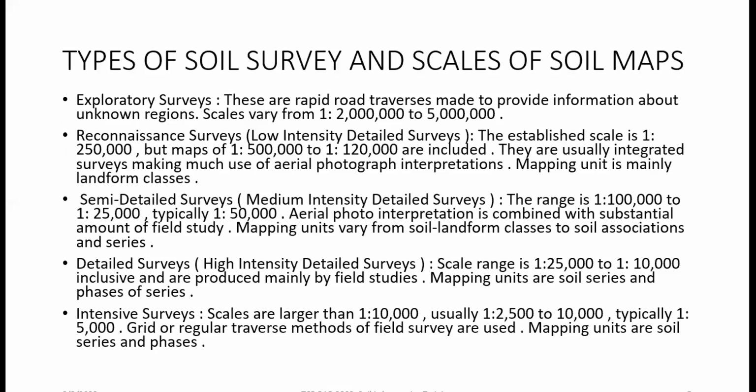Also, if there are changes in slope, where this area is low and this one is high, you can take a sample at the low one and another sample at the elevated or high soil. We call this stratified sampling or physiographic sampling, based on visible changes.